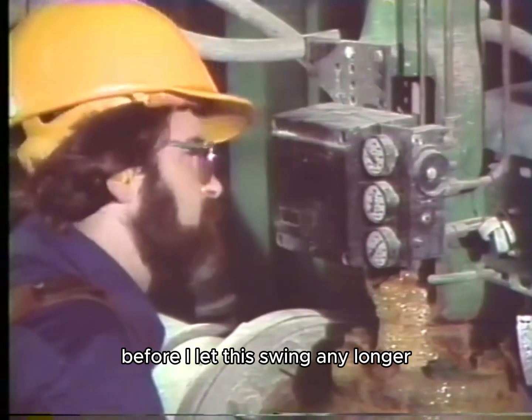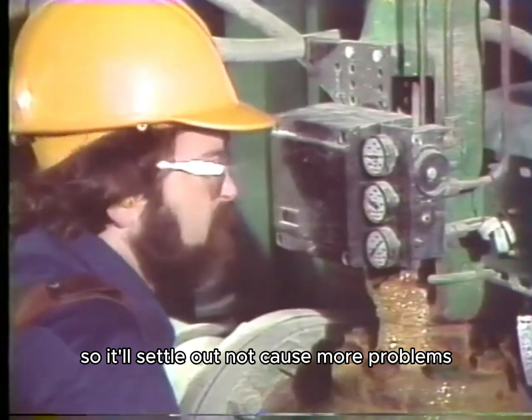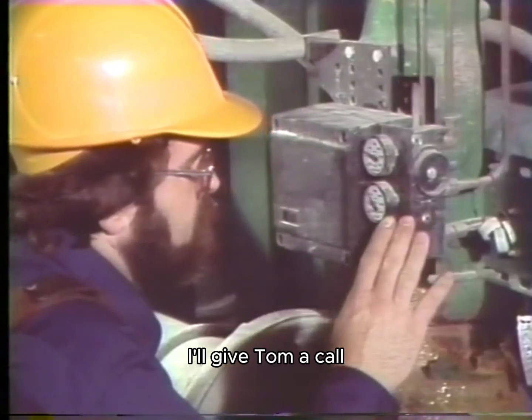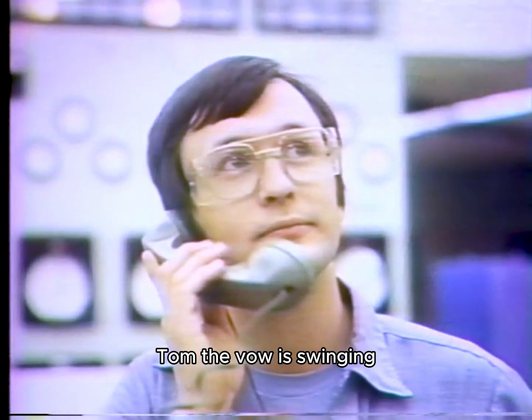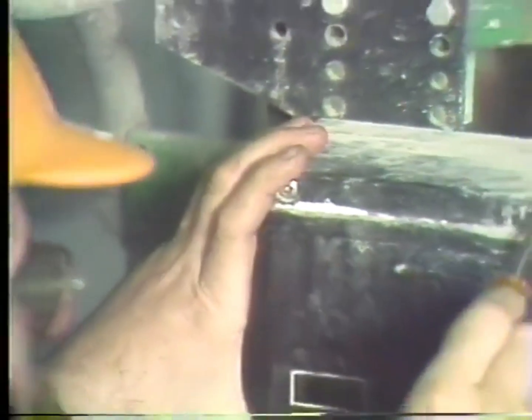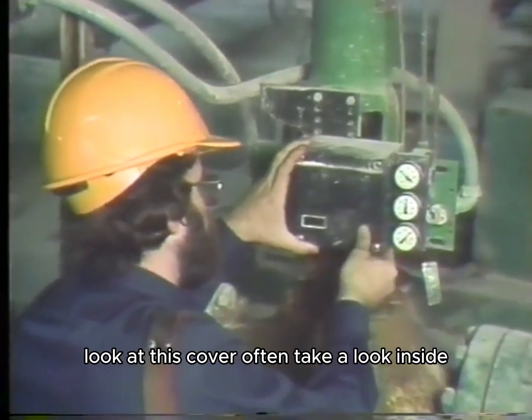Before I let this swing any longer, I'll get the system placed back on manual so it'll settle out and not cause more problems. I'll give Tom a call. Tom, the valve's swinging. Put it in manual. I'll check the positioner now. I'll get this cover off and take a look inside.